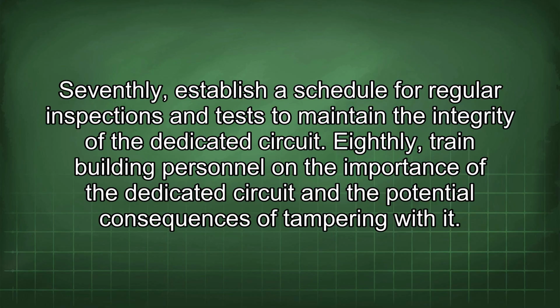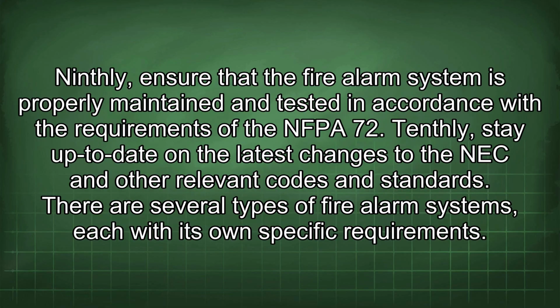Eighthly, train building personnel on the importance of the dedicated circuit and the potential consequences of tampering with it. Ninthly, ensure that the fire alarm system is properly maintained and tested in accordance with the requirements of the NFPA 72. Tenthly, stay up to date on the latest changes to the NEC and other relevant codes and standards.